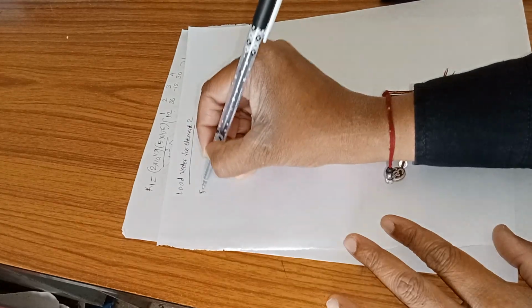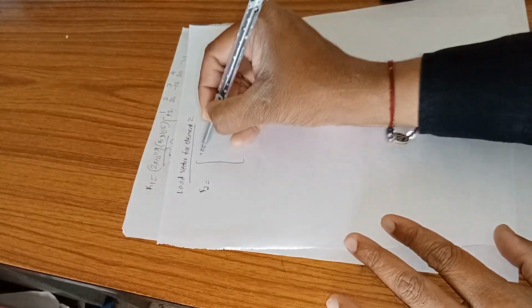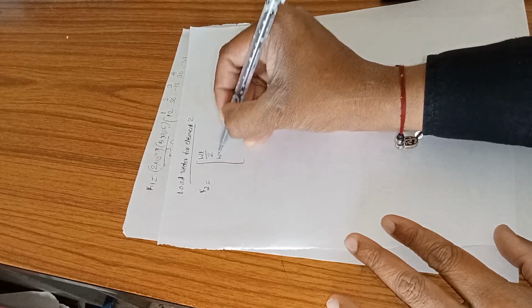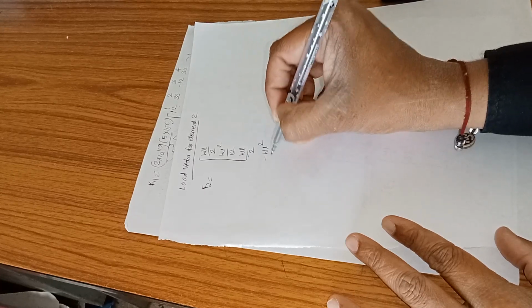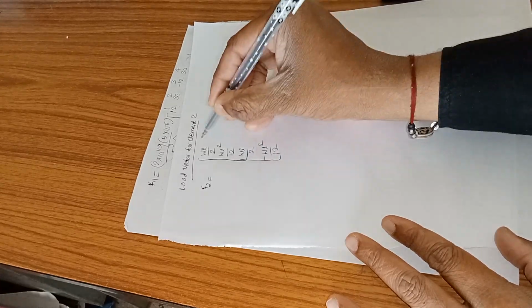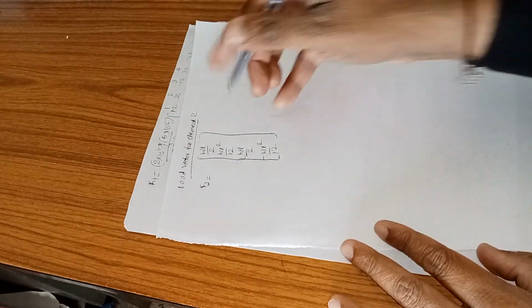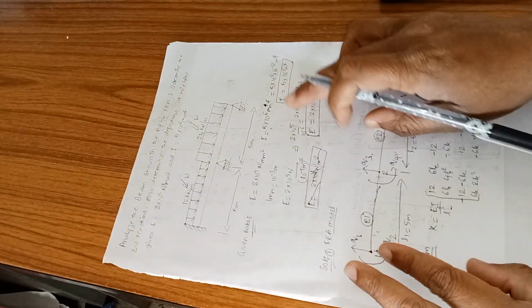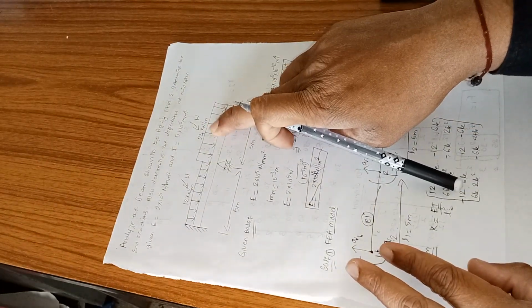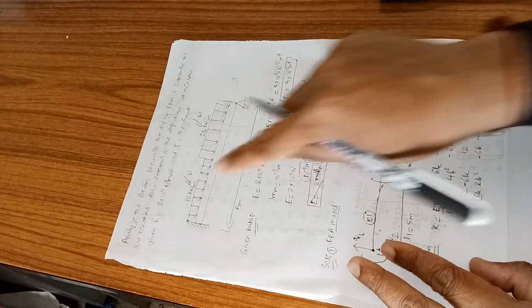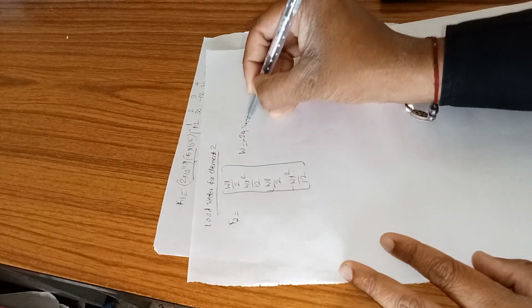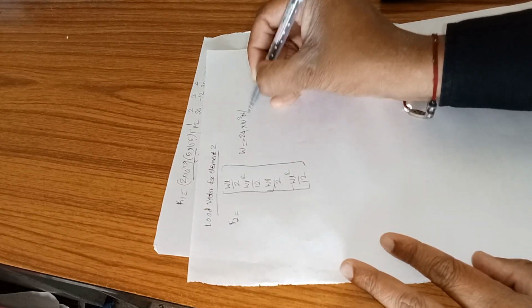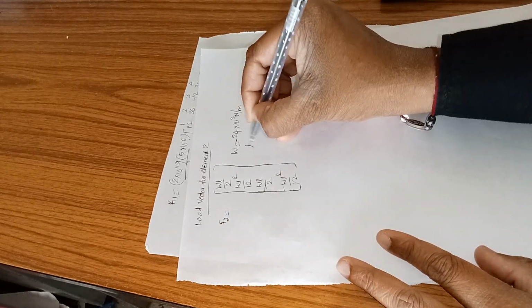So for element 2, I'm just going to indicate it like this. The formula is going to remain the same anyway: WL by 2, WL square by 12, WL by 2 and minus WL square by 12. So this is the formula list. And here the W value is going to be 24 because it is clearly mentioned in the problem itself. You can see here that this is the value of W for element 2. For element 1 it was 12 and for element 2 it is 24. It's going to be minus 24 into 10 to the power of 3 Newton per meter. And the L value is going to be 5 meters.